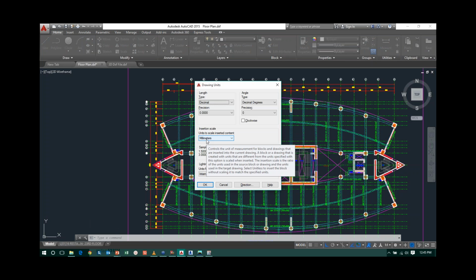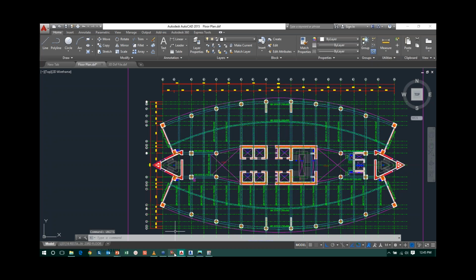And again, if you are trying to import multiple floor levels from AutoCAD DXF, where each floor plan is different, then all the floors should have one common point, which should be aligned for all the floors. If not, then they will be taken at different positions. So there are a couple of things you need to consider. One is the unit system consistency. The second thing is the base point for all the AutoCAD drawings should be the same for all the floors. Now, once the unit system is matching, I can go to MIDAS